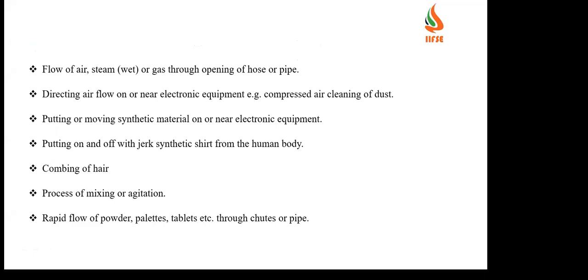Then another activity: flow of air, steam and also gas to the opening of a hose or a pipe. So we have seen the gas leakage, the steam leaks also will generate it, and also direct air flow on or near electronic equipment, like compressed air and cleaning of the dust. In that case also there will be a chance of generation due to the two dissimilar materials. And putting or moving a synthetic material on or near the electronic equipment.